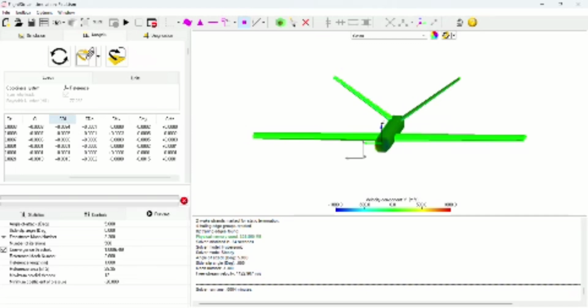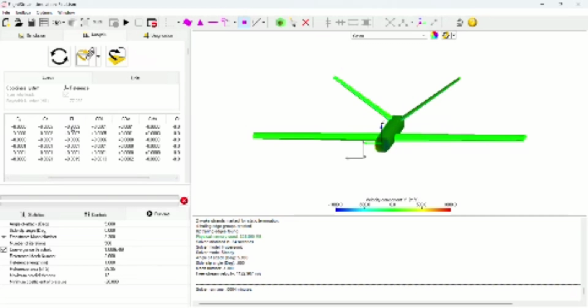Again, when we go to the analytical results and refresh it, we have the CX, CY, CZ values based on the axes. Mainly we have CDI, CDO and CL values. So those numbers can be evaluated, or you can use it to compare between subsonic and hypersonic or any other different results what you have got, may it be theoretically also.